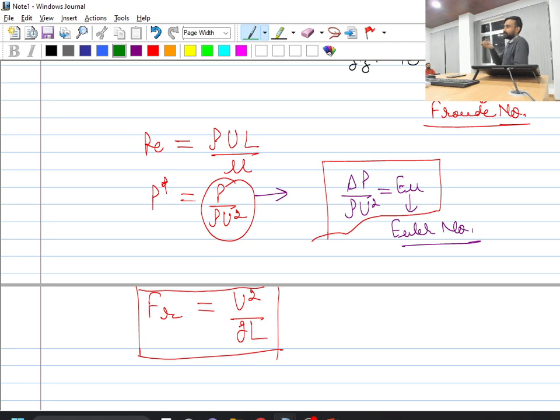So it is associated with the motion of the fluid mass, and viscosity is associated with the dissipation, viscous dissipation within the fluid mass. So the Reynolds number gives you the relative importance between inertia and the viscous forces, because its numerator represents inertia forces and the denominator represents the viscous dissipation, because the important term coming in its denominator is actually viscosity.